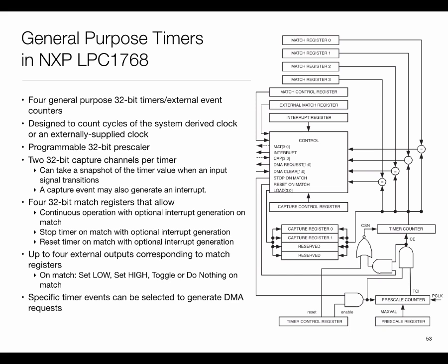And the way to generate these things is using a counter. If you were to do it purely in a program, what you would do is set the signal to be high and wake me up in period times the analog value that I want to convey. So if I want to convey 50%, I would say wake me up after T over 2, and then bring the signal down, and then again arrange to wake up when I need to bring the signal back up. You could do it in a software intensive fashion. You'll have a lot of interrupts happening at a very rapid rate. And this is a very commonly encountered operation.